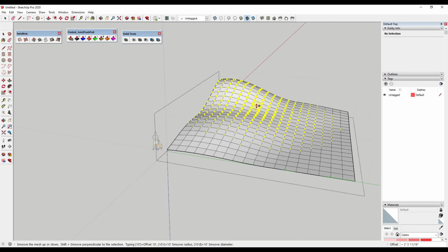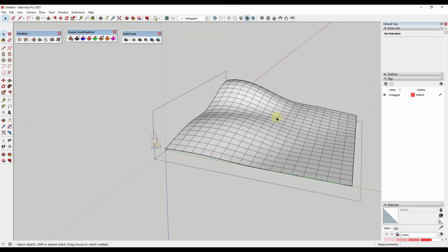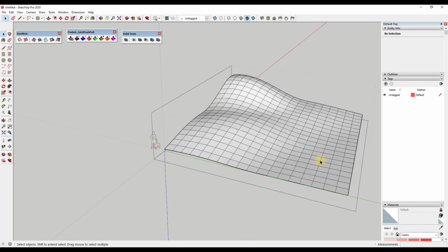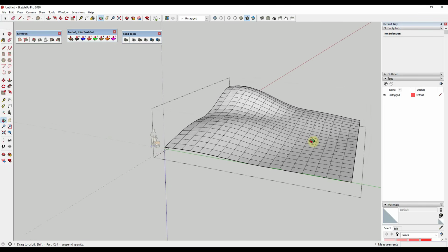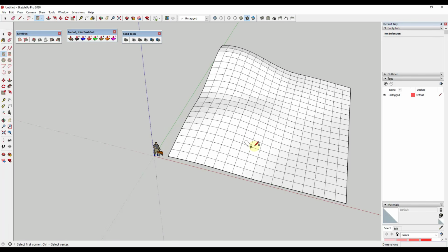And so let's say that you've got this hilly terrain in here, and you want to create a flat area inside of this terrain. Now the assumption is you're not going to be able to cut the whole hill out, right? So you're going to have some kind of a wall on the back side. The way that I like to do this is to use booleans or to use solid tools. And the way that I like to do that is I like to model out where my site would go. So for example, I'll draw a rectangle, assuming my house was going to go maybe right here.